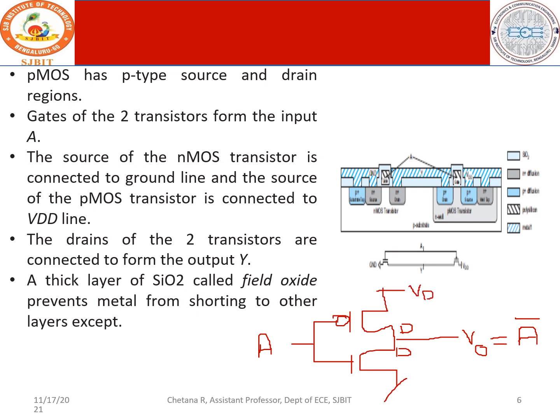Now which are the terminals which should go to VDD? Which are the terminals which should go to VSS? Since the output is taken at the drain junction, obviously the other terminal left out is the source. In CMOS, this is the pull-up region, and the pull-up region is always PMOS.